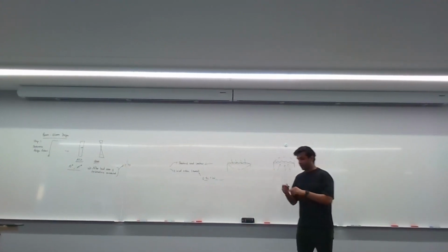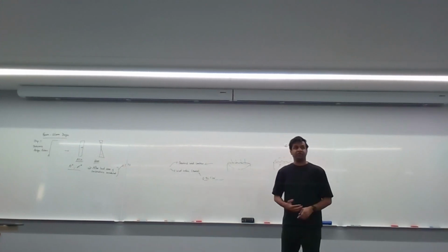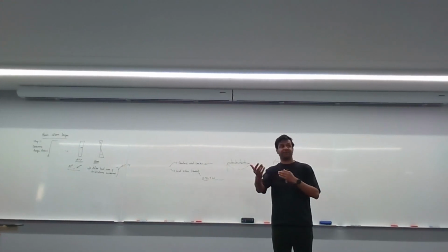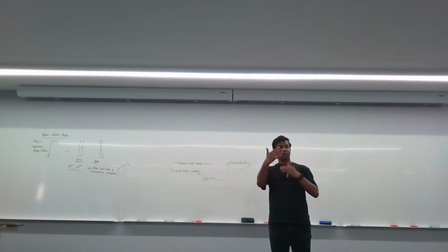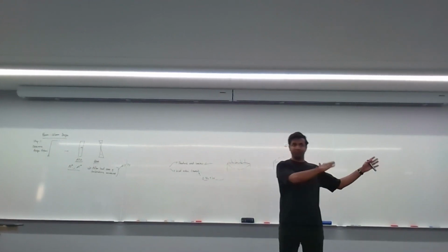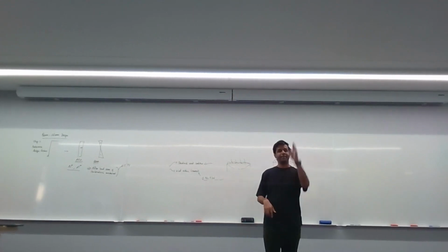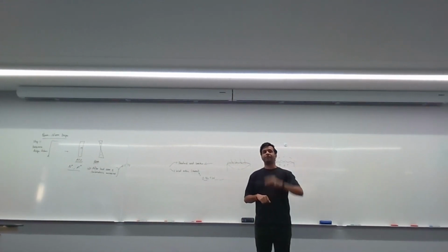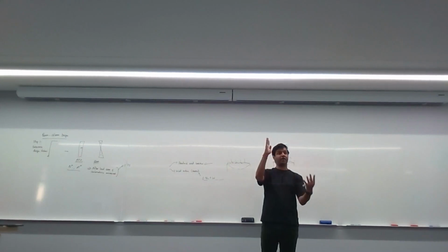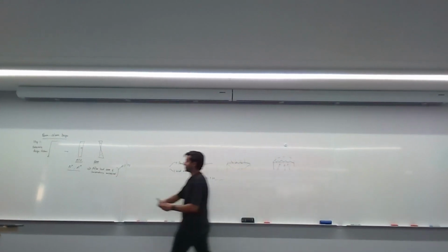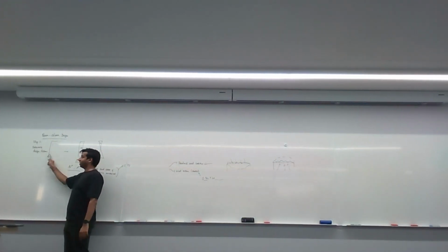And usually when the wind load is given to you, right? If the direction isn't specified, then you have to do two cases. Assume it's blowing in one direction, and then assume it's blowing in the other direction, right? Now, for a beam column, remember, if the wind is blowing upwards, so let's say this is the roof. This is the beam column I'm designing.